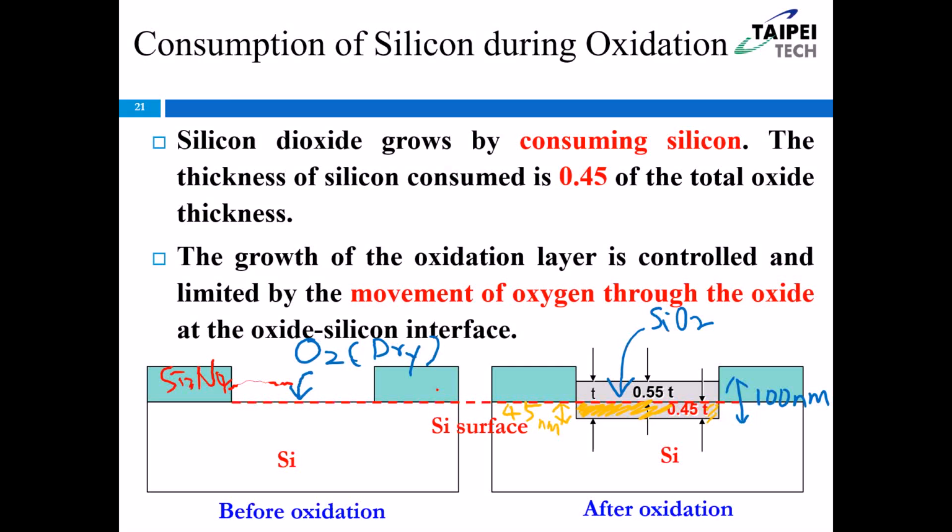Compared to the silicon nitride, silicon is a softer material, and silicon nitride is a harder material. 硬度比较大. So I cannot put the silicon nitride on the silicon directly. Between those two materials, we need a buffer layer. Do you still remember which buffer layer we use? Like the pad oxide, screen oxide, right? Or whatever you call it, it's the silicon dioxide, okay?